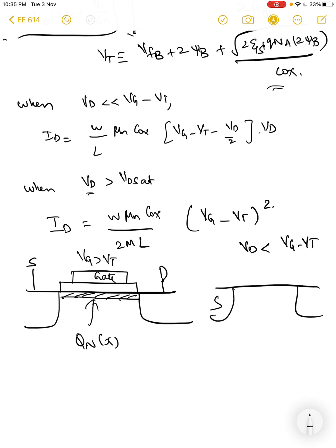the same source and the drain, but then the channel is slightly reduced near the drain side because the drain source junction is reverse biased. We also saw the band structure where the conduction band and the valence band are all lowered by the applied drain potential, and there can be a region in which the intrinsic energy level of the semiconductor bulk close to the drain is slightly above the Fermi level, giving you a loss of inversion, right?